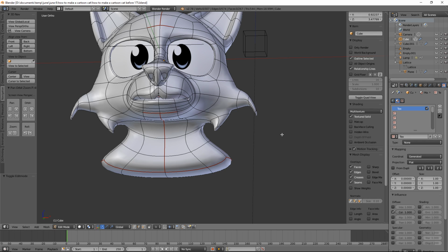Okay, when you're laying out your UV seams, you're basically trying to put seams in places where, for lack of a better word, there's a lot of 3D-ness to your mesh. And you're doing that just so that your mesh lays out as easily as possible flat, so it makes it easy to lay it out flat.